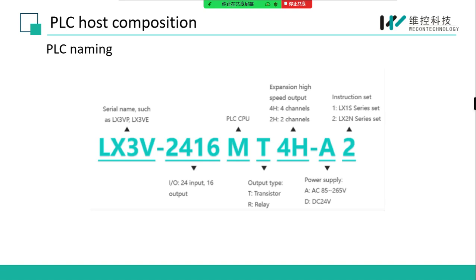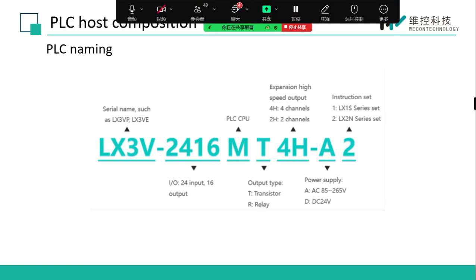For the same PLC, you can also use Y2 and Y3 to produce pulses. But due to the hardware difference, the output frequency cannot be guaranteed above 20,000 Hertz.